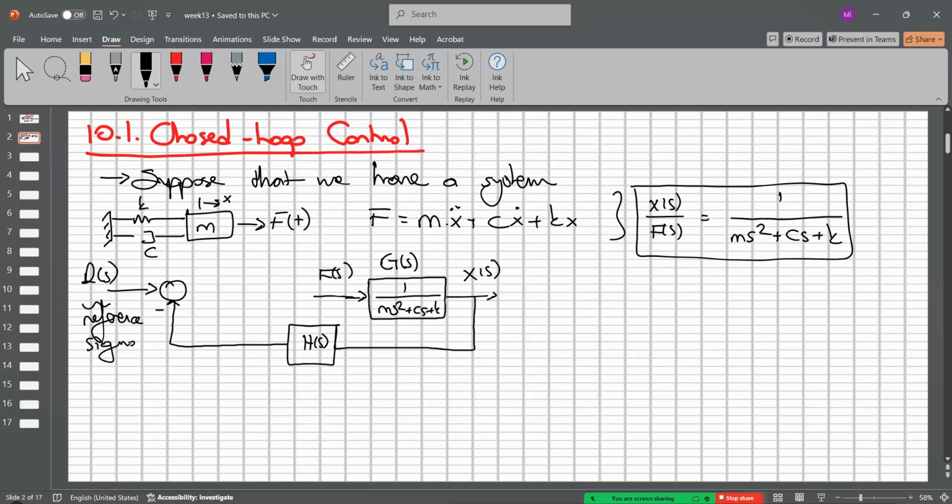Okay, we call it the reference, so we have a desired x value, or the position value, and we feed it in here. This X(s) can be measured by using the sensors in here, just like this one. This is the sensor, and the sensor also has a model in here, and this is the continuous plant, okay. And also we need to derive these algorithms in here. This is the error signal, because the reference minus our current position gives us the error for a desired position. And so how can we condition this system? We set another block in here which is designed by ourselves. We should call it what? The C(s). And also this is, for example, a driver. Okay? But the driver also has time dependency or time properties based on this information.